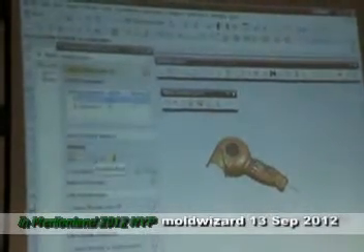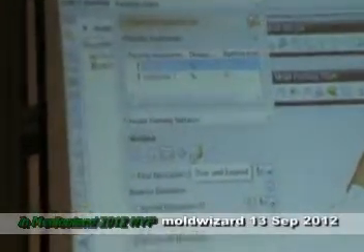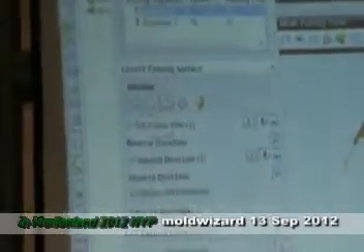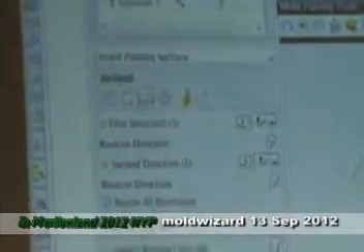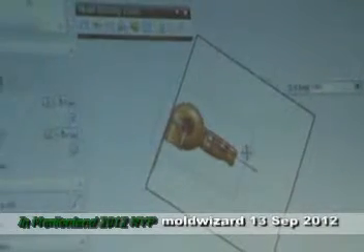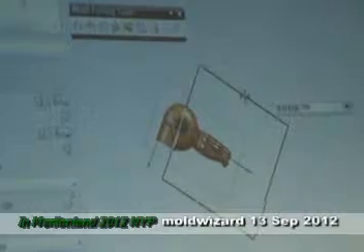You can use a planar bounded plane. Because it's a planar face, it's flat, so I will use this. Most of the time the system will decide automatically, but this time it did not, so I choose this. This part I need to enlarge. Remember to enlarge this main parting surface. How large? As long as this surface is big enough to cover the block, you can stop.